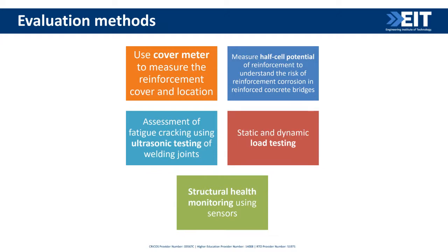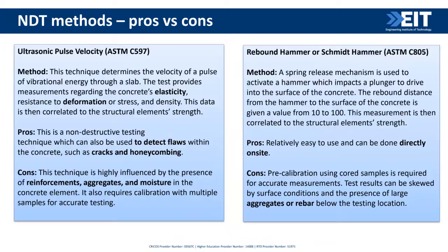We can conduct both static and dynamic loading tests. We can also assess cracking. We can use ultrasonic testing, depending on the situation, to identify cracks. And at the end of this session, we will be discussing a bit more in terms of structural health monitoring, how sensors are helping us to monitor the structural capacity in real time. So let's have a look at some of them.